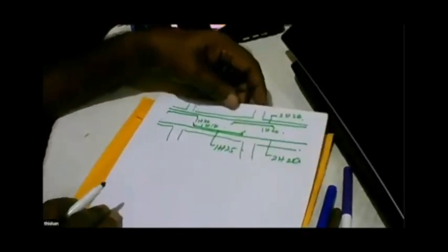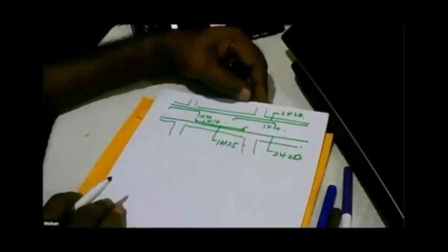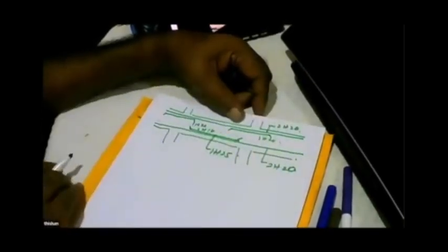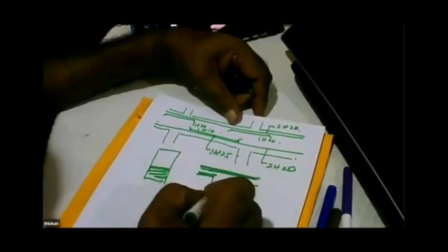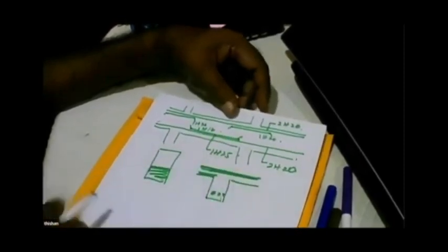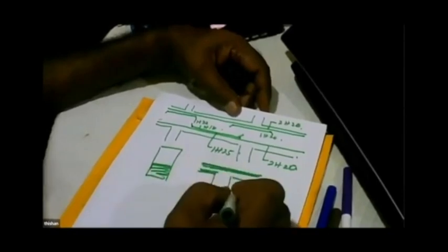Can you see how I detail the beam? Because I don't mind providing less here, because I am providing more here. I am providing less in a less efficient section, and more in a very efficient section. So which will have a higher increase in moment capacity?